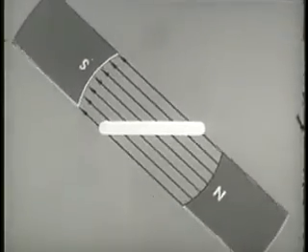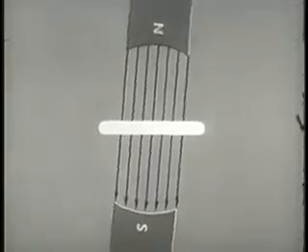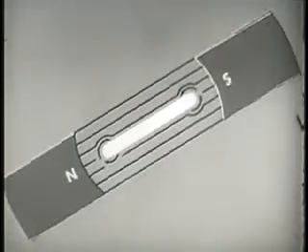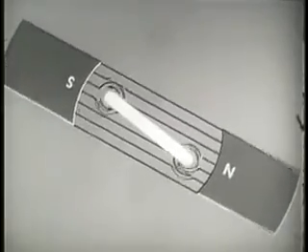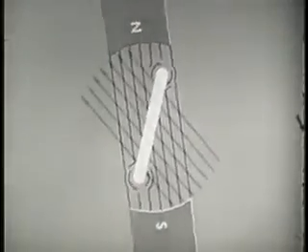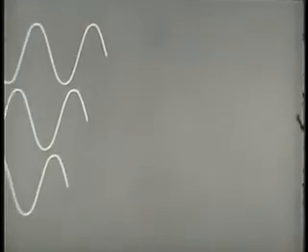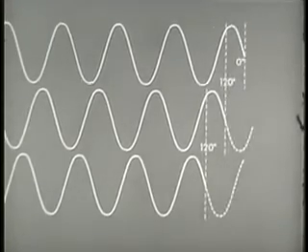For if the rotor stops while the field continues to turn, relative motion will have been re-established. Lines of force are being cut once more. An EMF is generated and the resultant magnetic field will cause the rotor to move again. So far, we have rotated the field by physical means, which is impractical. It is necessary to find a way to rotate the field electrically. We saw earlier how three voltages 120 degrees out of phase were generated. This voltage can be used to rotate the field electrically.